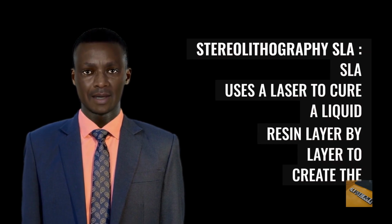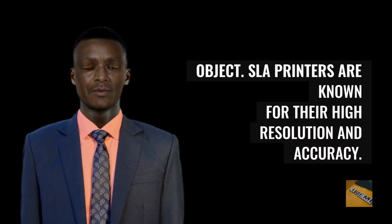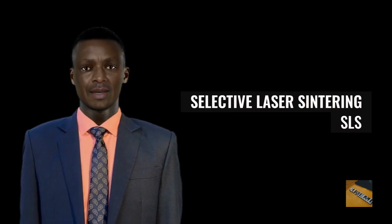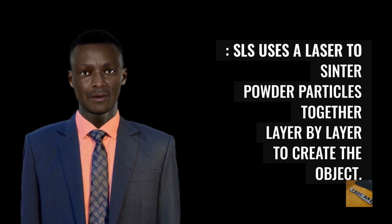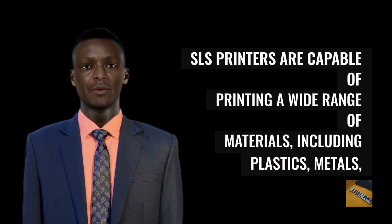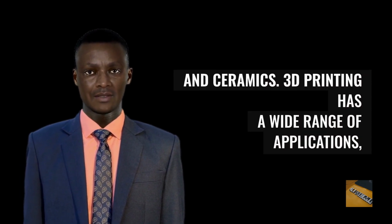Stereolithography (SLA). SLA uses a laser to cure a liquid resin layer by layer to create the object. SLA printers are known for their high resolution and accuracy. Selective laser sintering (SLS). SLS uses a laser to sinter powder particles together layer by layer to create the object. SLS printers are capable of printing a wide range of materials, including plastics, metals, and ceramics.